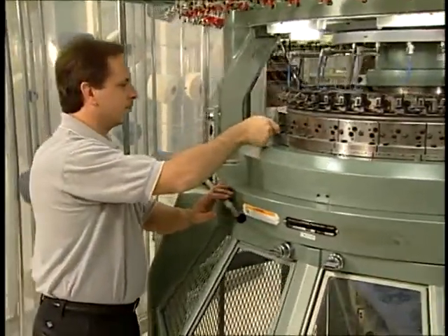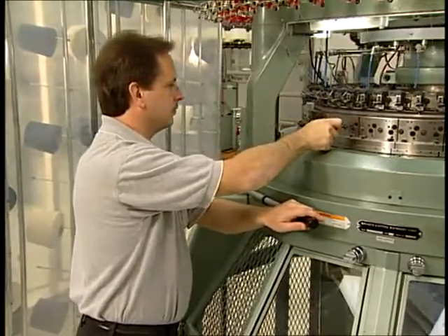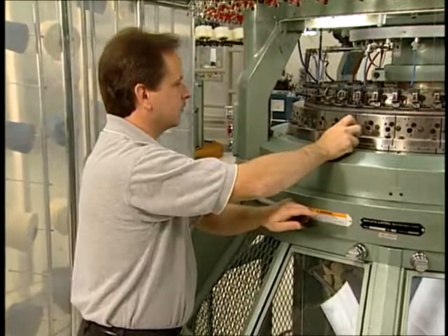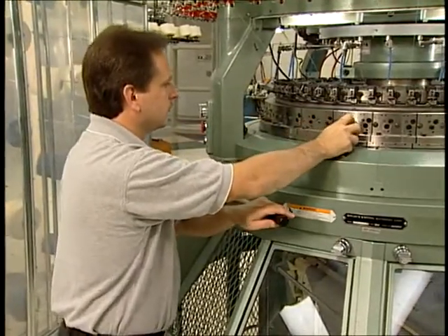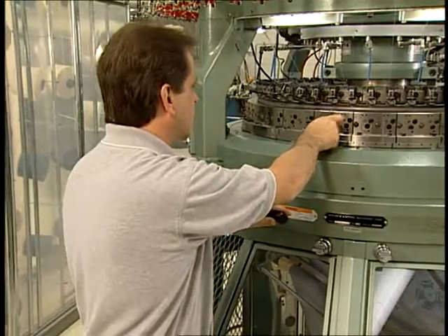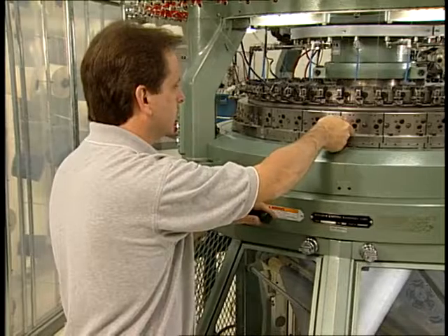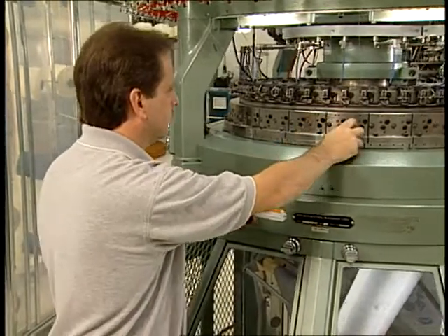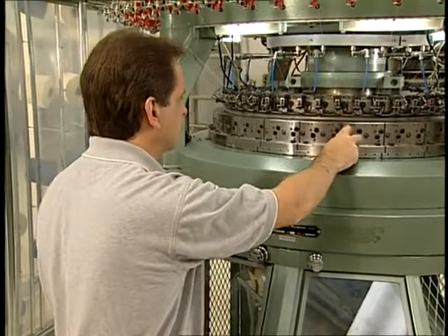The variables the knitter has to consider are the yarn type, machine cut, machine cylinder diameter, and the stitch or course length at which the yarn is knitted. The machine cut and cylinder diameter will determine the total number of needles in the cylinder. A knitter may rely on his experience or a computer prediction program to determine the ratio of the variables that will be used for manufacturing the product.